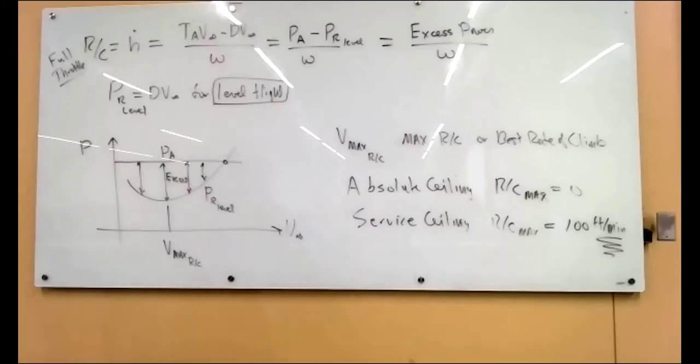I mean, you can go wild and do a little tiny tail really far back, but then your fuselage is long. Yeah. So you just go based on what airplanes look like. Okay. And we should try and optimize the fuselage diameter and length in order to make the coefficient of drag as small as possible. Yeah. Right? Okay. I see.